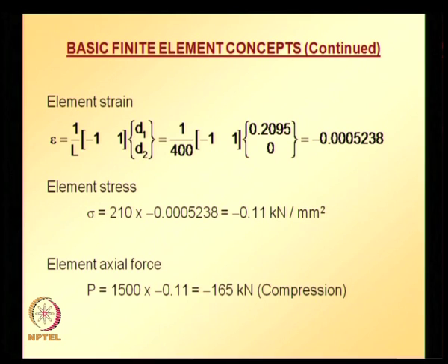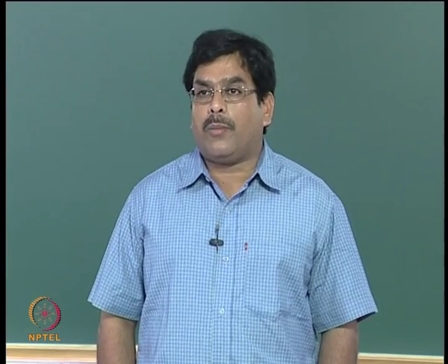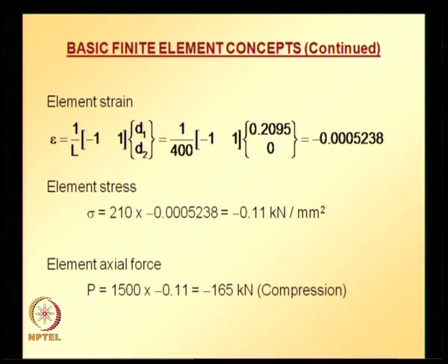So now we have just seen how to solve 2D truss problems. In a similar manner a truss having any number of elements can be analyzed. And now let us first derive the equation system for a 3D space truss problem, whereas 2D truss is a plane truss, 3D truss is going to be a space truss. A 3-dimensional space truss element can be developed using a coordinate transformation and using the local elemental equation for axial deformation element in the manner which we did for the 2D plane truss element.